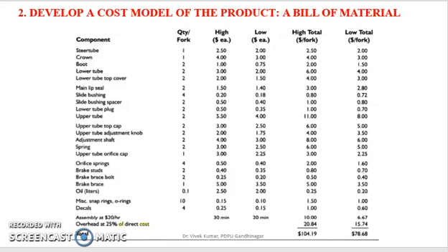For most products, the first estimate of manufacturing costs is completed by drafting a bill of materials and estimating a purchase price or fabrication cost of each of the parts of a front suspension fork. A useful way to record cost information is to list figures for the high and the low estimate of each item. This helps the team to understand the range of uncertainties in the estimates.